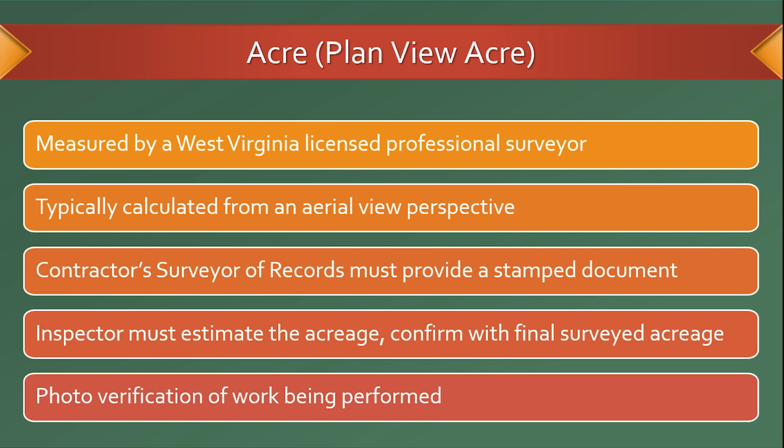Acre, also called Plan View Acre, must be measured by a West Virginia licensed professional surveyor and is typically calculated from an aerial view perspective. These calculations are generated from the surveyed boundaries both before and after construction. The contractor's surveyor of record is responsible for providing a professionally stamped document certifying the amount of acreage identified for